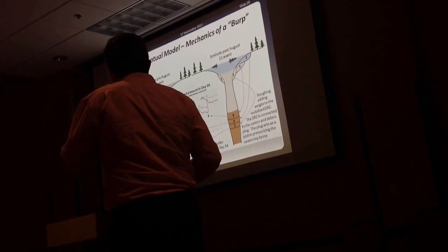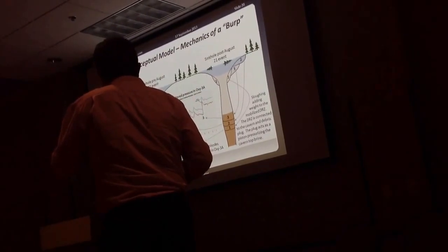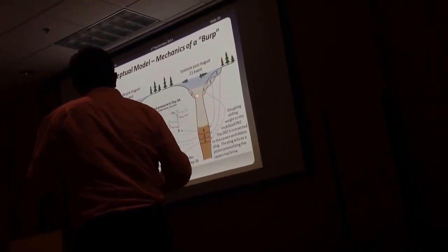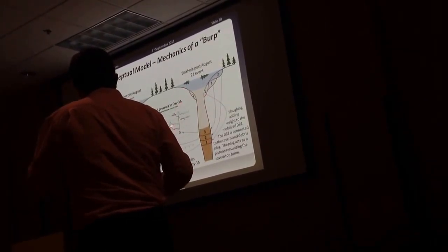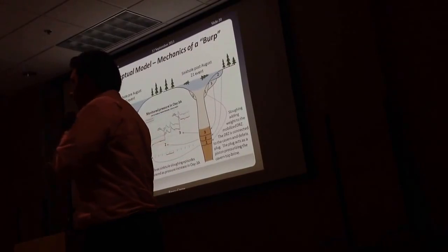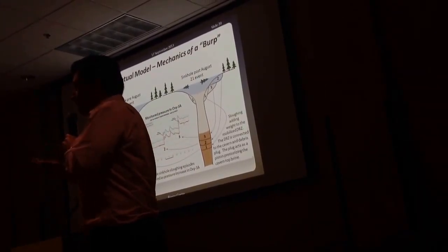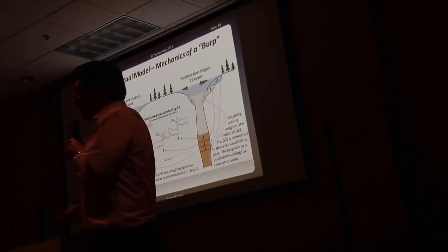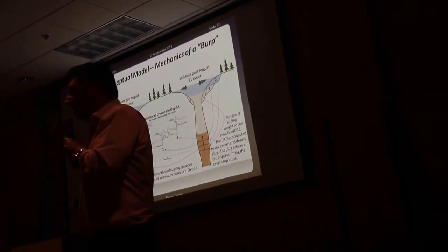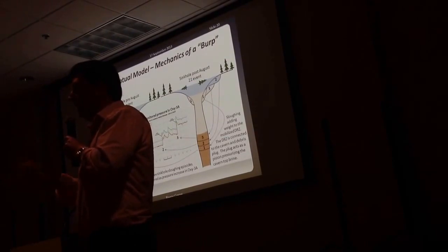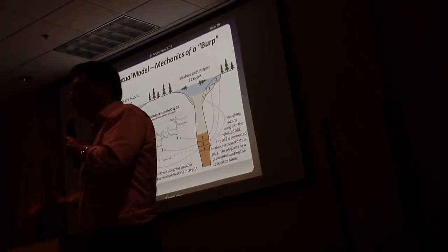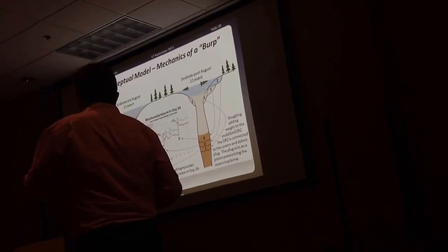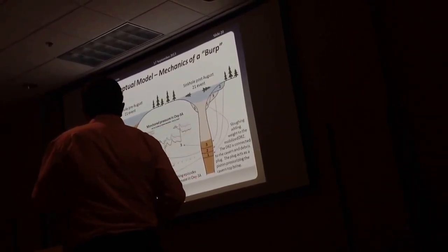So as this gas comes up, it triggers this sliding. This is what's shown on the other side of this diagram. In this particular event, what we saw was actually 3 slides that were very close to one another. This is the pressure recording from within the cavern. So that material that's sliding into the sinkhole is connecting via pressure through to the actual cavern, and we're recording that on the pressure instrumentation on that well Oxy3A.